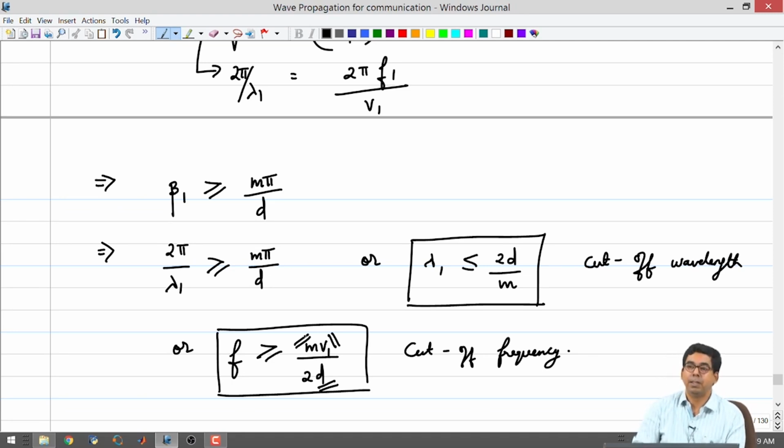So, you will have frequencies above this cutoff value being transmitted. If you have a system where multiple frequencies come into the picture and you want to make sure that you get only frequencies above something, say to remove noise, you could construct something like this and make sure that only the signal is going through. The assumption there is that signal frequency is higher than your noise frequency, which is not always the case, but it is a general assumption you can make, okay.